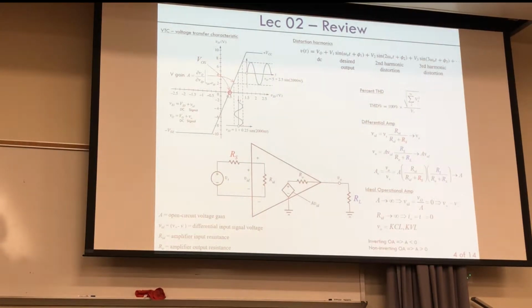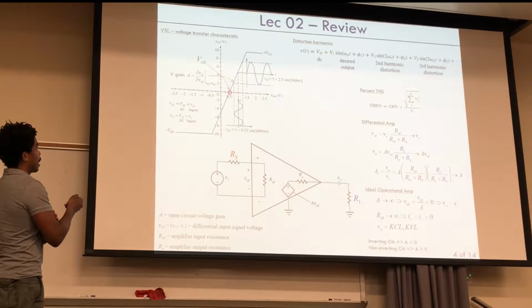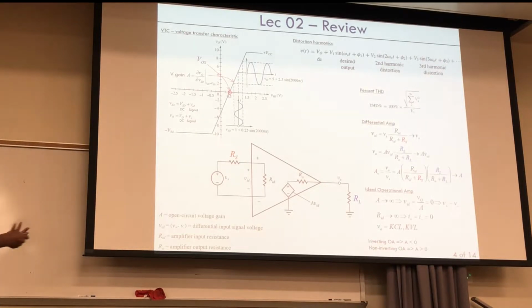And we also saw the case where if this amplitude was much larger than this little vertical dash line, maybe it went from right here and then was clipped off right here. And if that happened, that means that these peaks right here would be clipped off. These wouldn't, but these would be. And that's where you get your distortion.